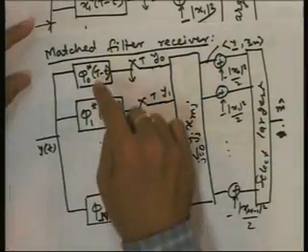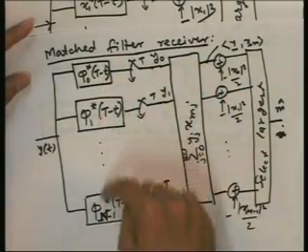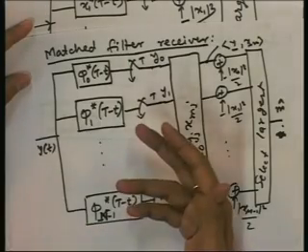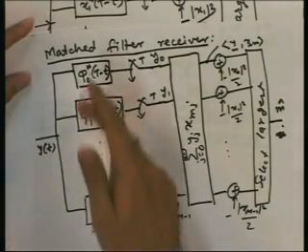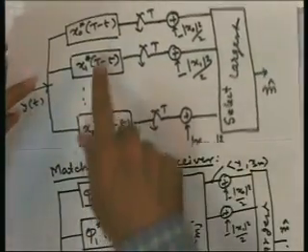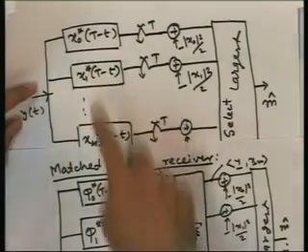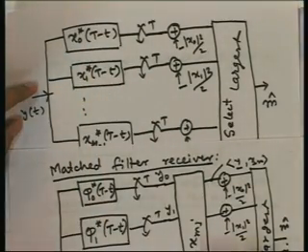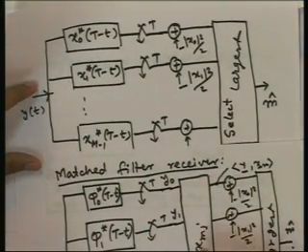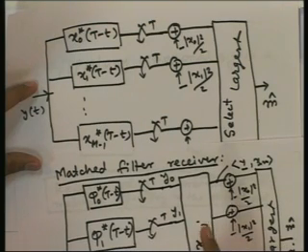So, for that particular case, we can say that these two receiver structures are of approximately same complexity. See, here also we will need n number of, so for orthogonal signal set m is equal to n. So, here and here we will require the same number of matched filters. But here we need to do all this, but here we will see that this xmj will be non-zero only for one particular j.